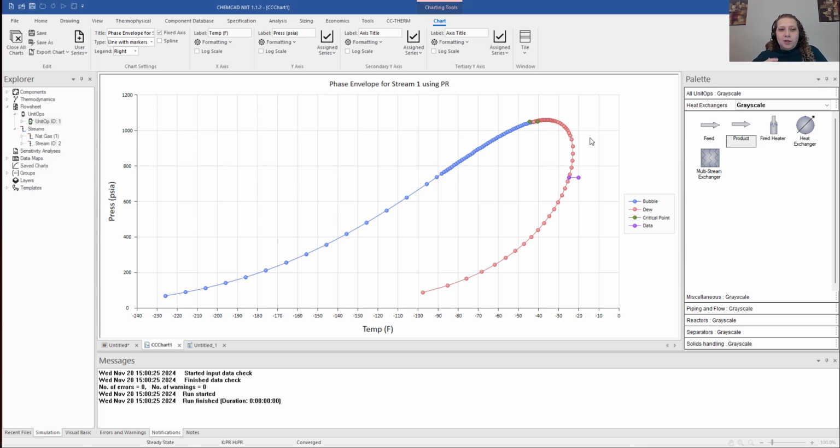I wish in the early part of my career I had used charts and reports and thermodynamic simulation a lot more in the early stages of a process to help me understand. So, for example, I was doing a lot of pump sizing and looking at these broader general processes, and my senior engineers would come and tell me just what to do, but I didn't understand the process enough. I didn't have enough internal knowledge about what's going on and what expectations I would have from the process. And so say if you're doing a pump calculation and you don't know where you lie in the phase envelope, you want to make sure that you're not going to cavitate your pump.